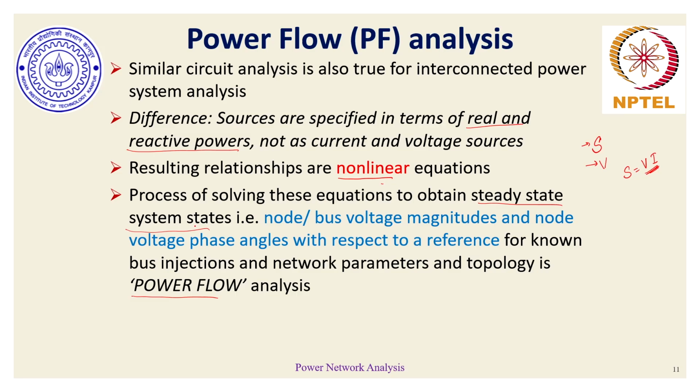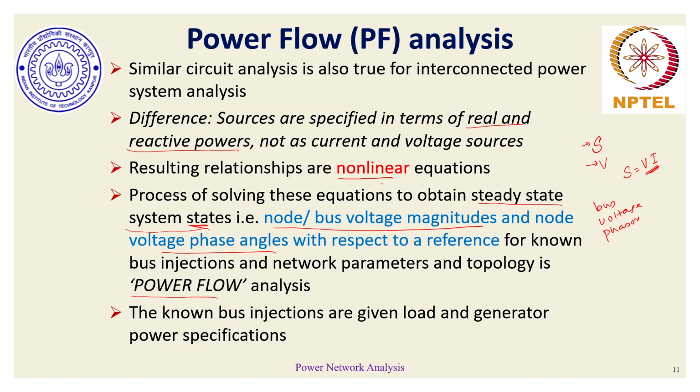And that's why these are called system states, which are nothing but the bus voltage magnitudes and phase angles with respect to a particular reference. Basically, we want to find the bus voltage phasor at all buses in the given power network, and to find that we have to solve certain nonlinear equations, and the process of solving this is essentially understood in this notion of power flow analysis. For applying power flow analysis, there is certain information which is needed.